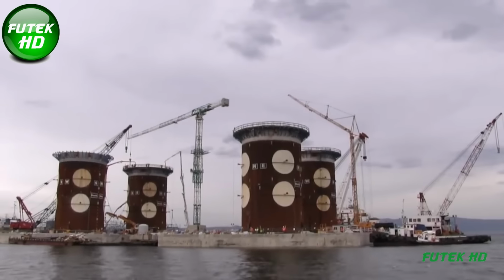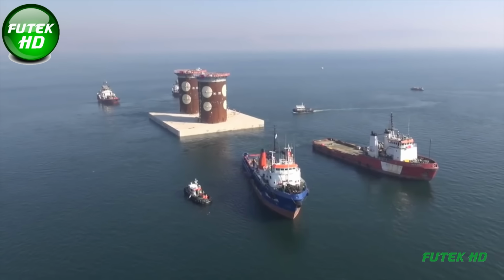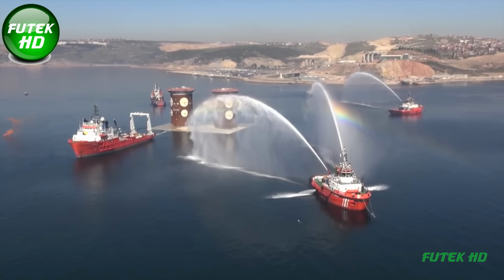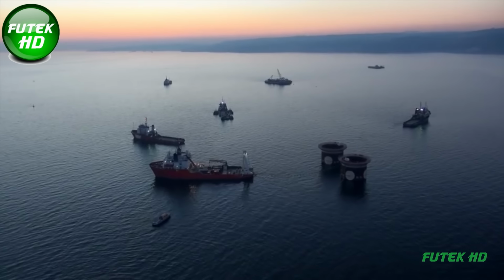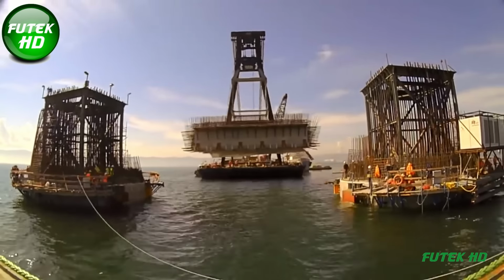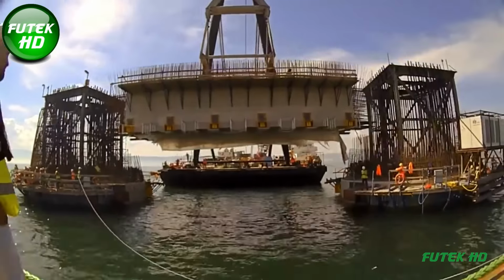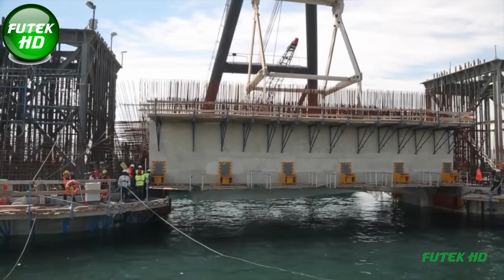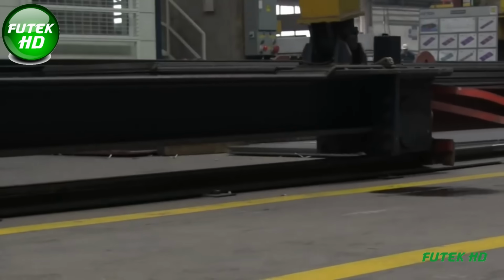The lower halves of the towers were lifted and placed using a 1,200-ton floating crane. For the upper sections, a jib climbing crane was used, which was installed on a horizontal beam lower in the structure. This dual crane approach enabled the completion of both the north and south main towers within just 6 months, a remarkable feat in large-scale infrastructure projects.